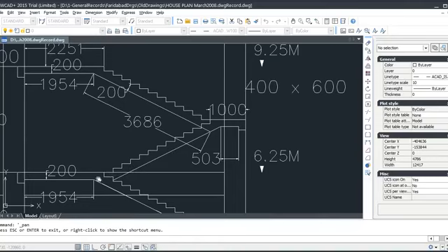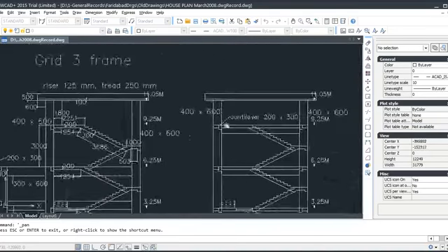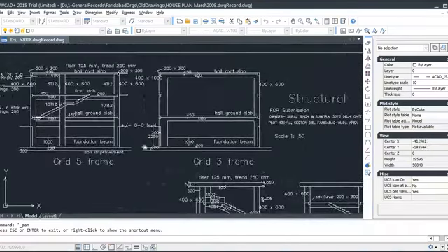Similarly, dowel means extension of bars which are not concreted but they are embedded in this landing and beam. These go up, you prepare, and then you pour complete like this. Remember, it's monolithic connection. It is not separate connection. And if you take 2 flights, then you cast here, then prepare for construction joint, prepare well, and then cast this one. This is generally done like that. And purpose of this was to show you triangles.